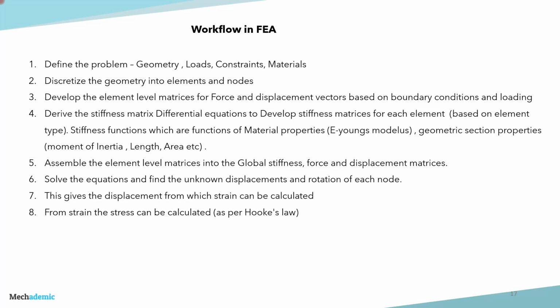So the matrices are developed and then the boundary conditions and loading conditions are applied. And as we had earlier seen, some values might become 0, some values might be known with the input of the loads, while most of the values will be unknown. So developing the element level matrices for force and displacement vectors is the next step, and applying the boundary conditions and loading conditions on them. The next step is to derive the stiffness matrix from the differential equations for the elements which have been used.